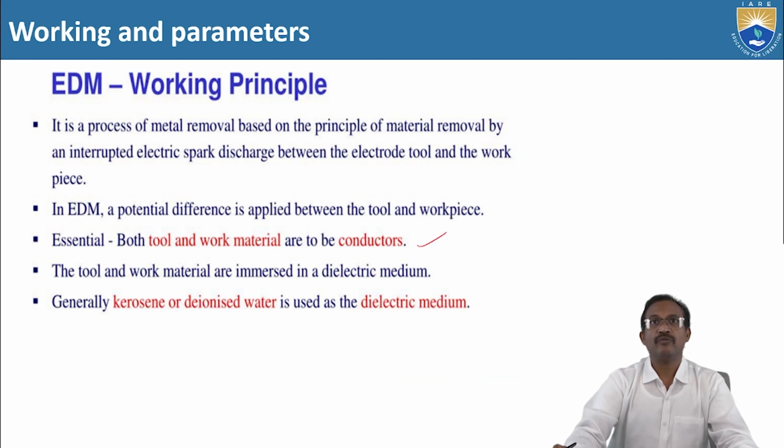Both tool and work material must be conductors. This is essential, otherwise the electrons will not pass. The electrons need to be transferred from cathode to anode, so both materials must be conductors.